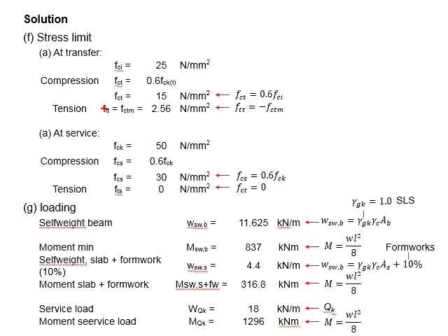Then we need to determine the tension limits, which is defined by its FCTM, which the formulas of FCTM can be referred from Eurocode 2, Part 1, Table 3.1. Assuming that the precast elements is fully prestressed, no tension stress is allowed.